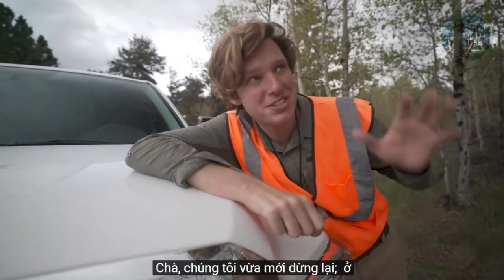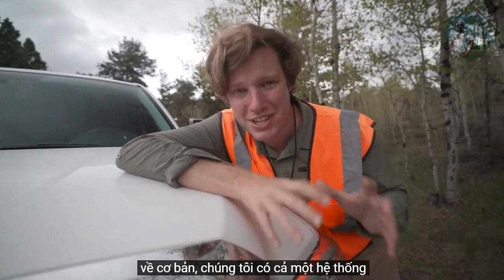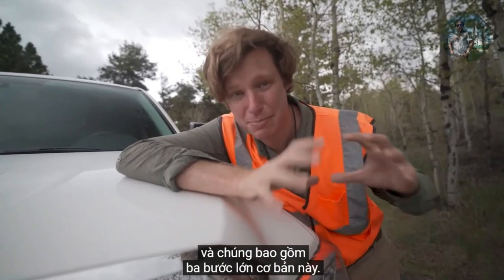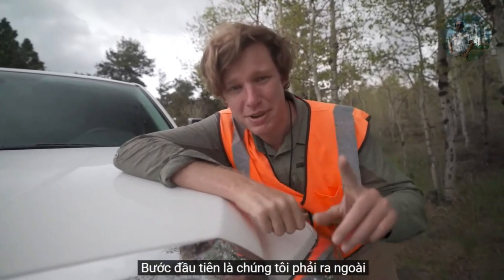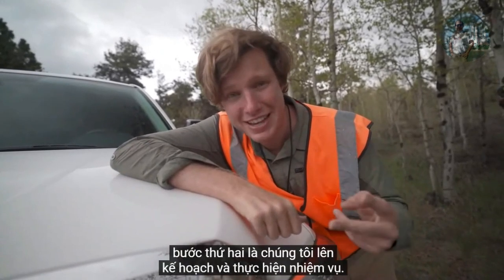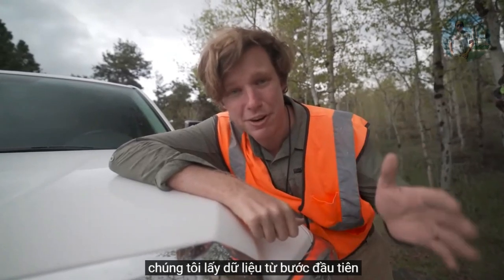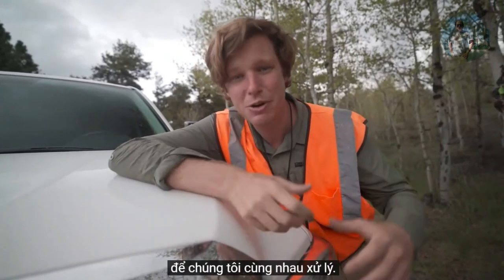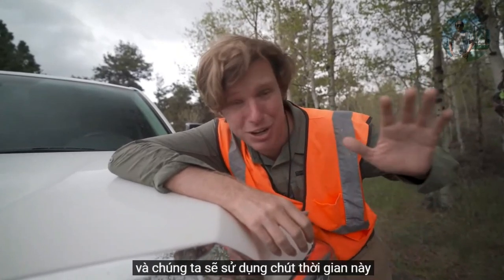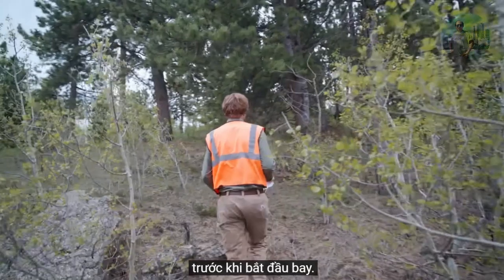Well, we just pulled up. It's starting to rain here. Before we start flying today, I want to tell you, basically we have a whole system for doing these LiDAR land surveys, and they consist of these three basic big steps. The first step is we have to go out and get ground control points and set up aerial targets. In the second step, we plan and fly the mission. And in the third step, we take the data from the first and the second step back to the office, and we process it together. But before we do any of that, we got to get out of this rain, and we're going to use some of this time to go and inspect and scout out the area before we start flying.